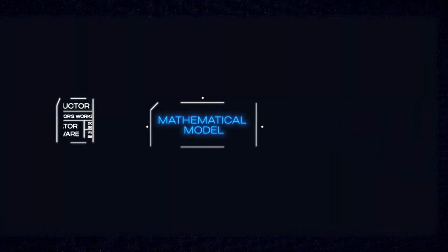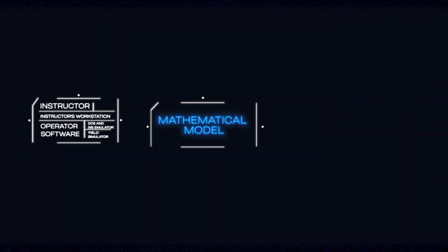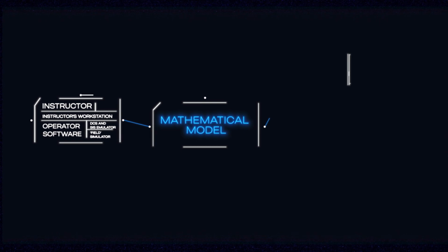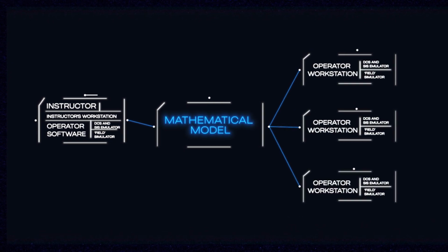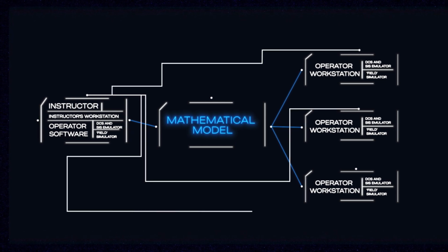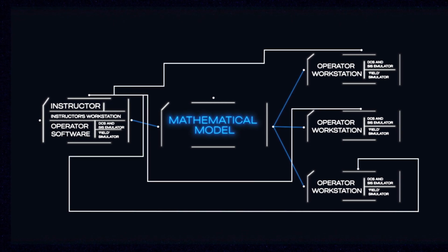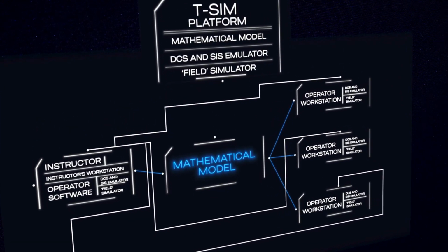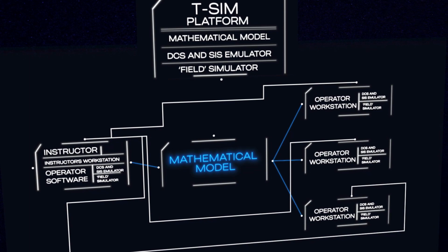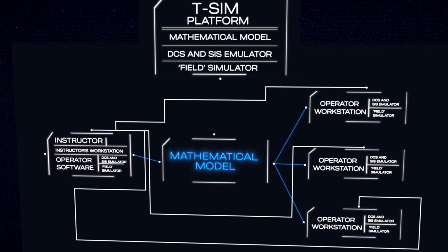The instructor's station is equipped with Universal Operator Station software, allowing the instructor to fully monitor the progress of the technological process and make real-time adjustments. Any technological installation undergoes upgrades and improvements. Therefore, it is essential to continuously maintain the Operator Training Simulator, OTS, in an up-to-date state.